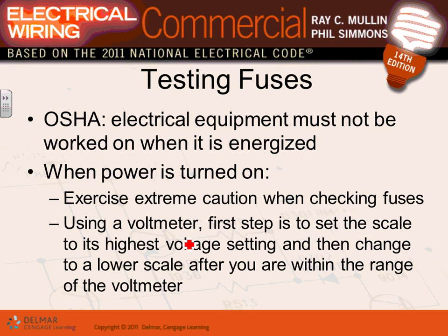When you test fuses, the first thing you need to do, guys, because of OSHA, is turn the power off. That's why we typically have a disconnect, where you disconnect the fuses and remove them safely. I know you're not electricians, but you can't even touch these if you're not an electrician, by law. You be very careful, guys. You walk into a place, you grab your voltmeter, you start doing measurements, it blows in your face. Your insurance might not cover you because you're there as a designer. You're not an electrician.